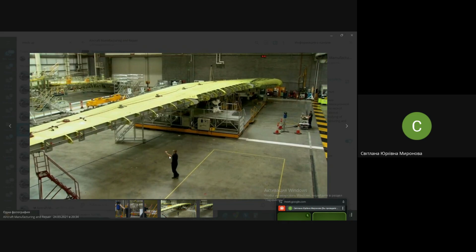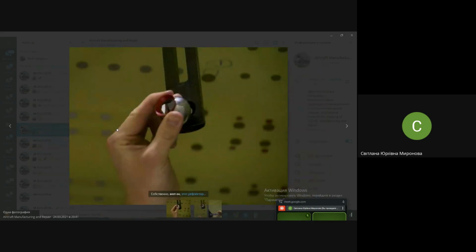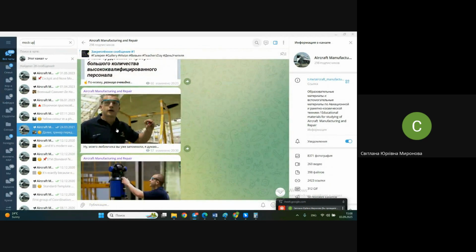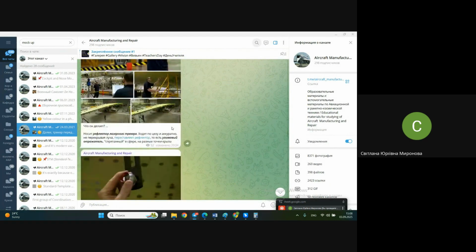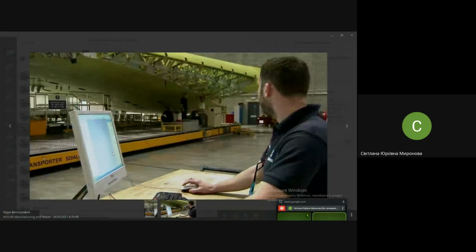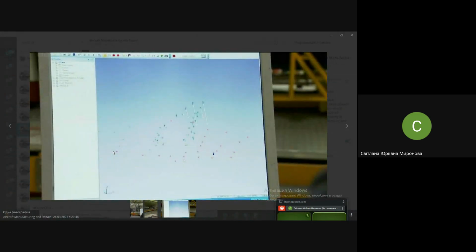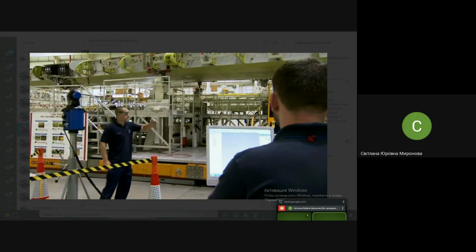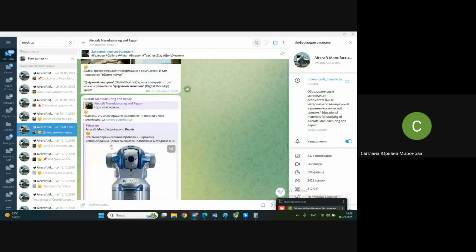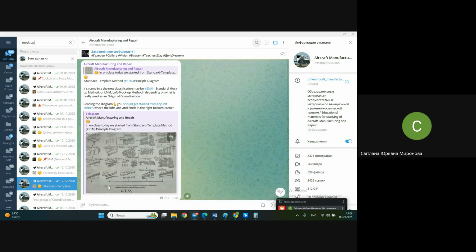And this is, you understand, the transporter of this reflector, this boy. With all the love for this boy, he may be replaced with another boy or with a robot or even with a trained dog, do forgive me, in order to place the reflector in another place like this. And next, the laser tracker informs about coordinates of these special places, and it's compared to the 3D model in the computer. And finally, that is not ideally visible, but visible, a so-called point cloud has appeared, and finally they may draw a conclusion about the quality of this aircraft.